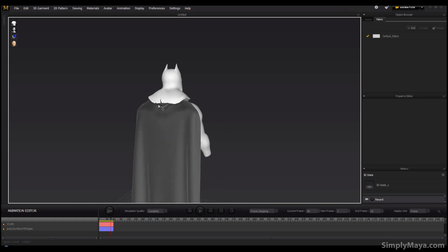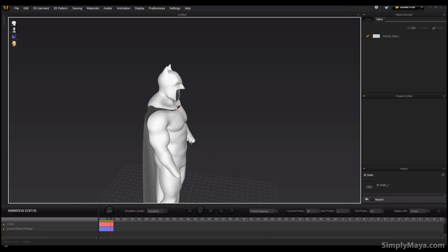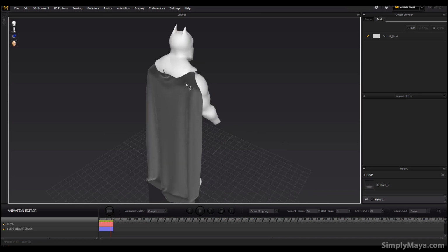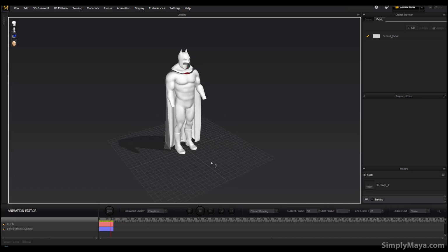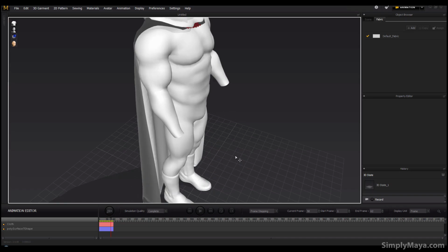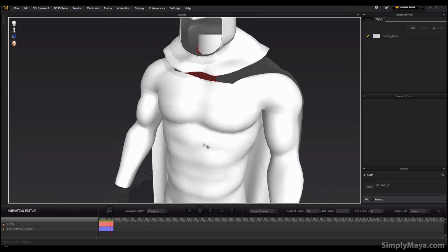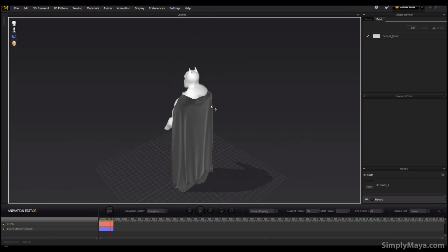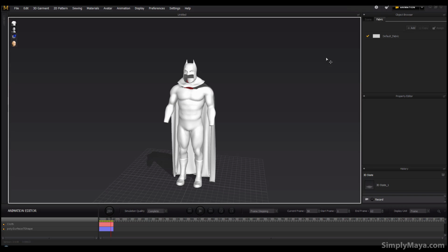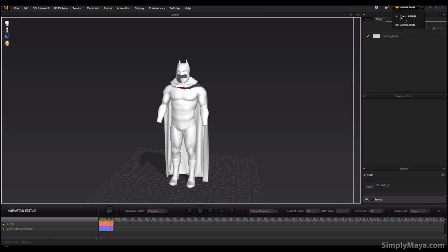What we want to do is blow this around in the wind a bit, and make sure that this cowl is in approximately the right place. Obviously some cleanup is going to have to be done afterwards, but generally that's close enough. And what a lot of people tend to do with stuff like this is scale down the cloth to 0.998 or something, ever so slightly shorter, which takes care of a lot of those intersection issues. But for right now, let's go back to simulation.